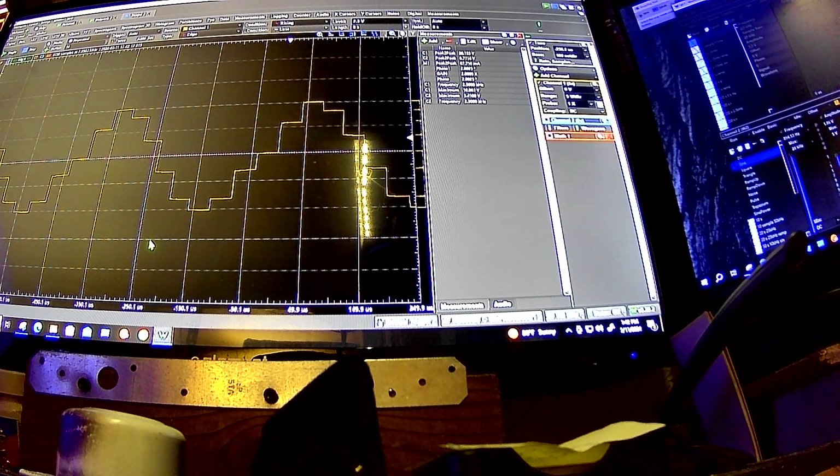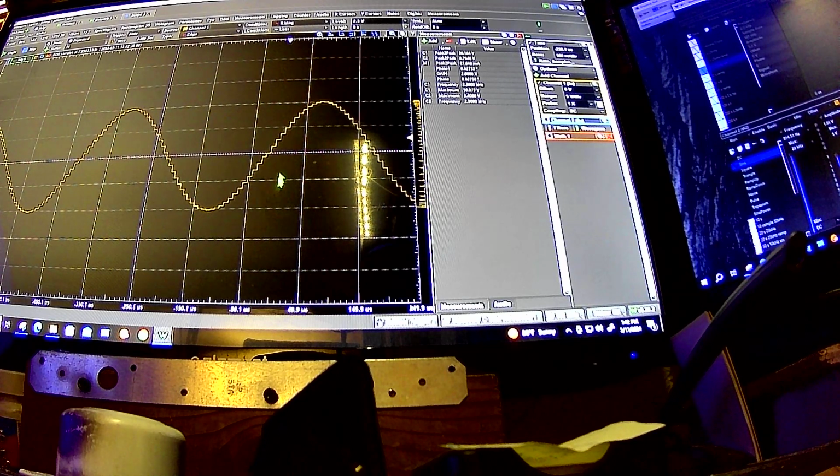And that's if you go rail to rail, obviously, because that's another thing. If you don't go as high, you usually lose resolution. But here the resolution's so low, I could actually make this signal a lot less than 20 volts peak to peak and not lose any resolution at all. Because it's only a couple of samples high or a couple of samples low, and even if we look at a 50 sample signal here like this, we got like 12 up and 12 down.